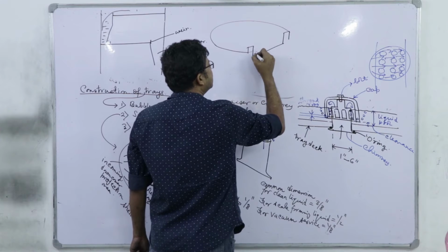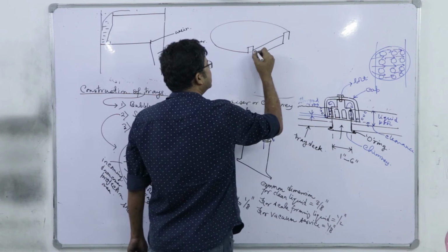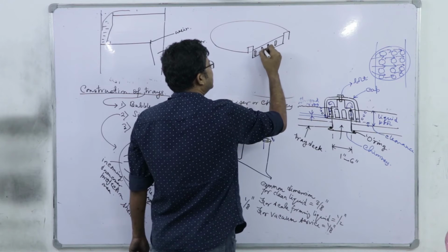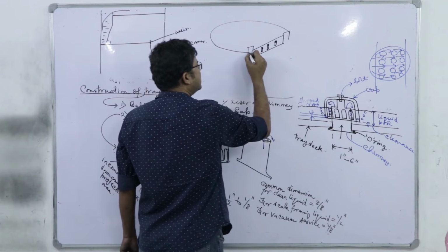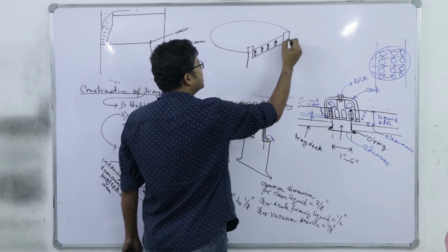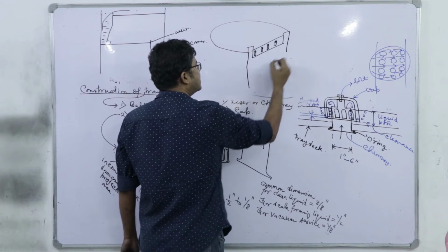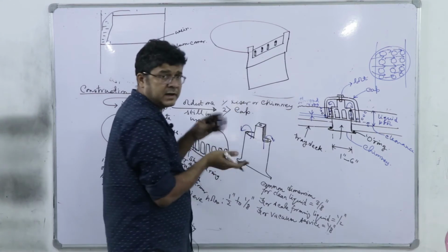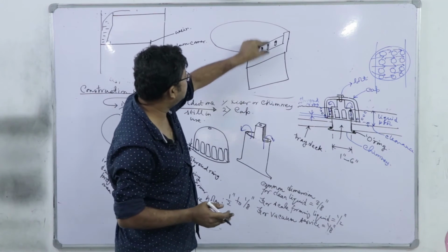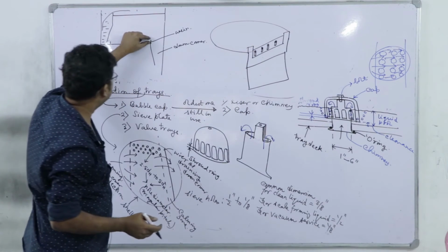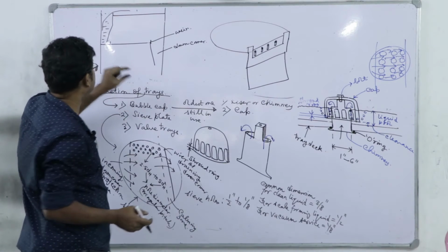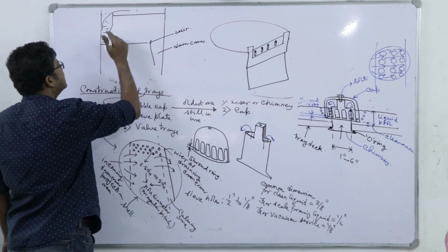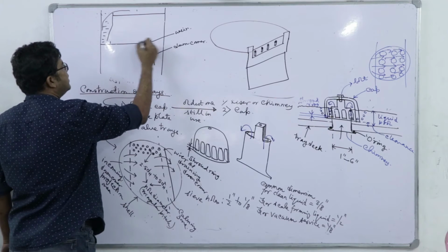And there is a slot which we can fix by bolts, and this is the downcomer plate, and this weir we can adjust in that slot upon adjusting the screw, and we can keep this height changing, similar here. So, what happens, why is this height being changed?